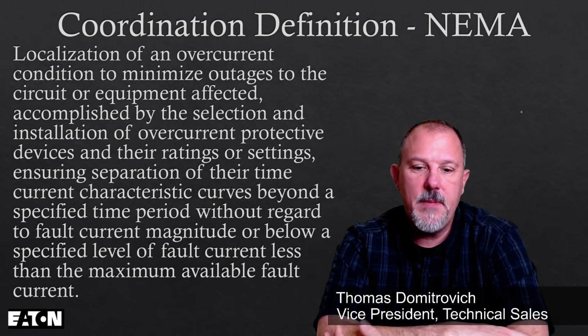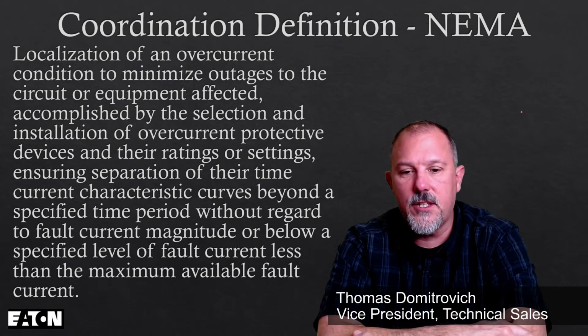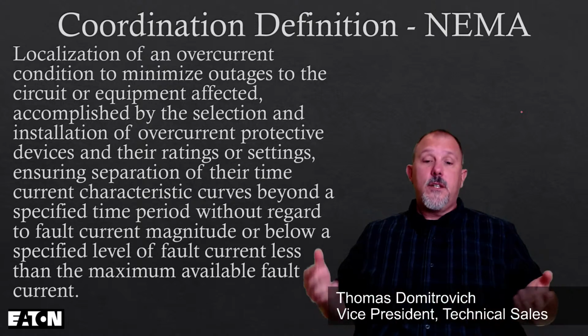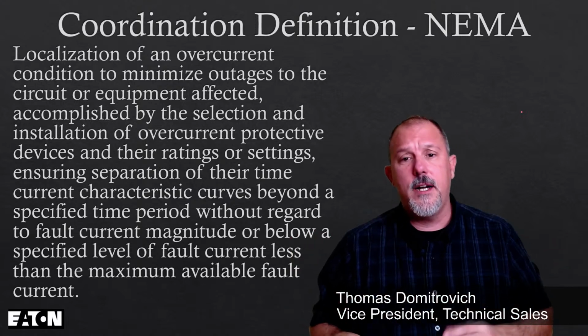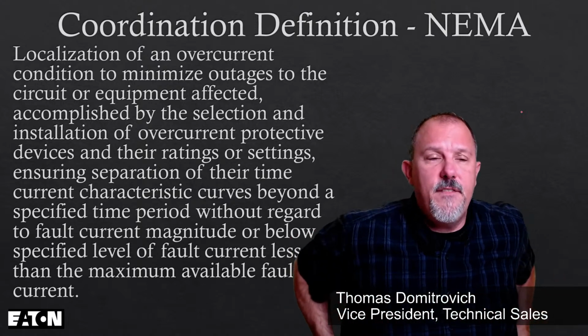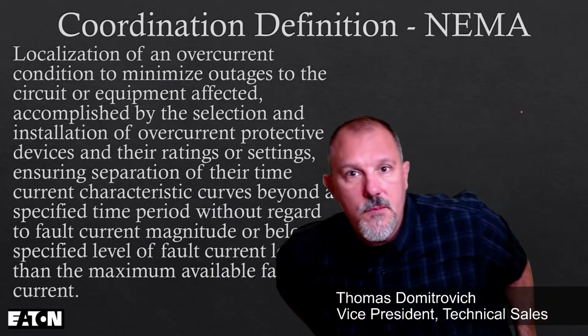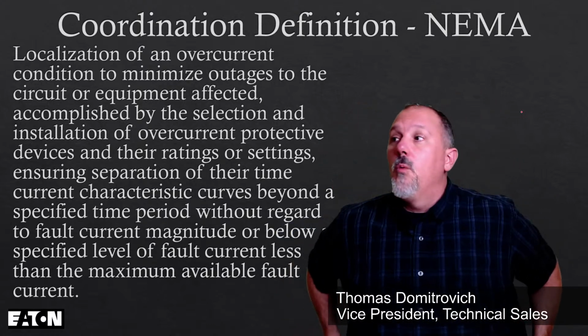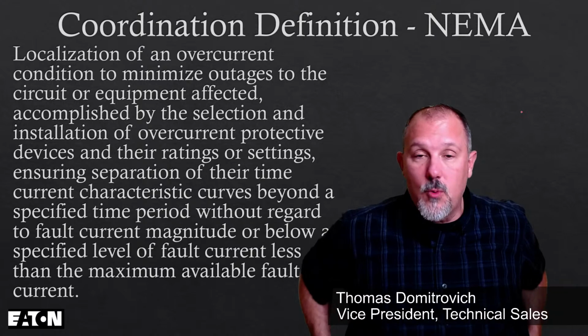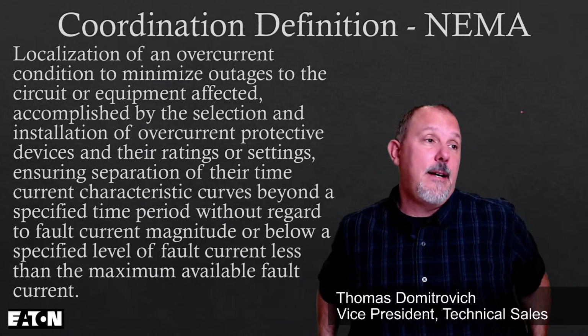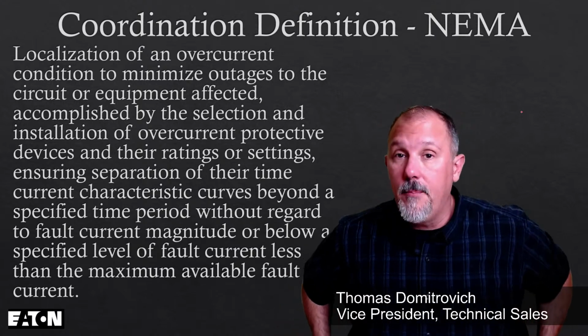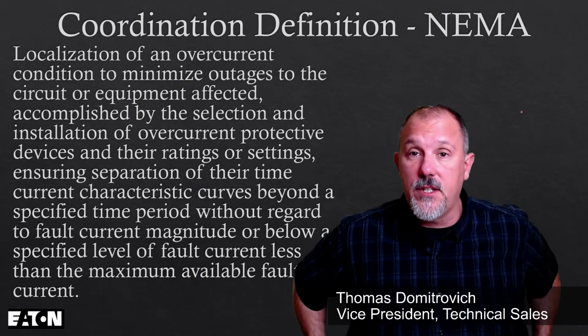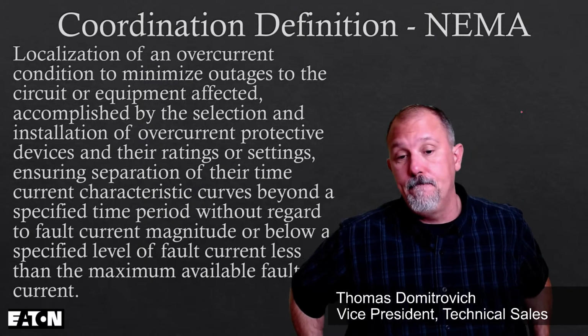So does any of this mean anything if condition of maintenance is not regularly applied? That's a good point, Robert. If I don't maintain my power distribution system, regardless of whether or not I selectively coordinated it or coordinated it, I may not be able to rely on the overcurrent protective devices to respond in a manner that they should.